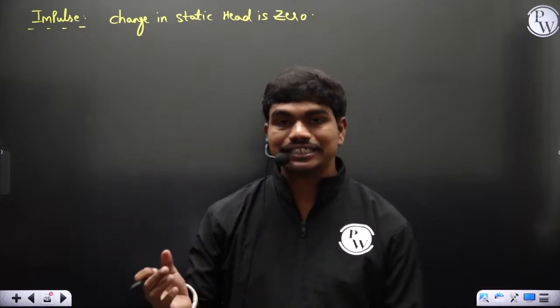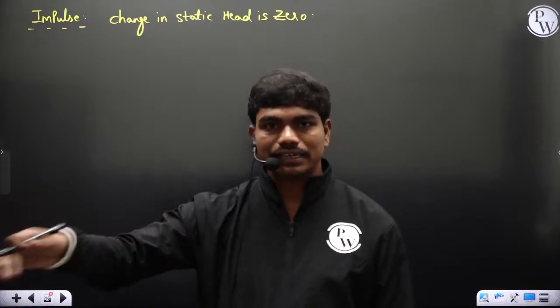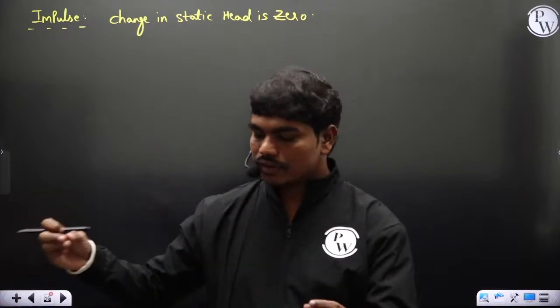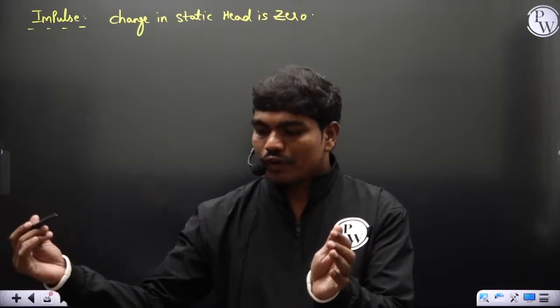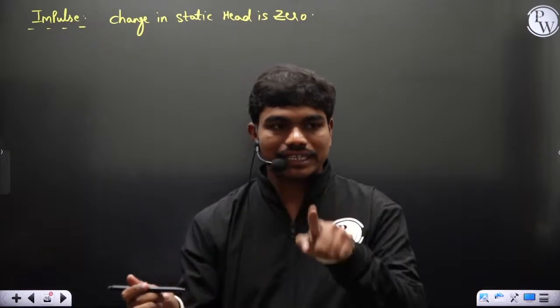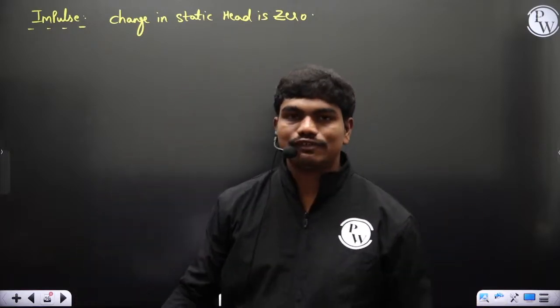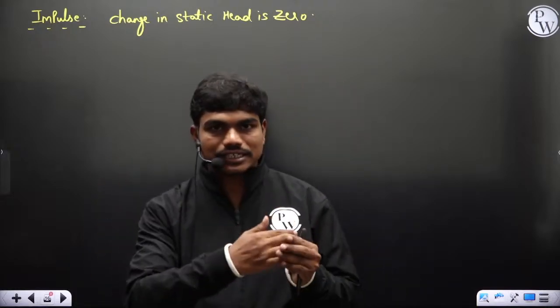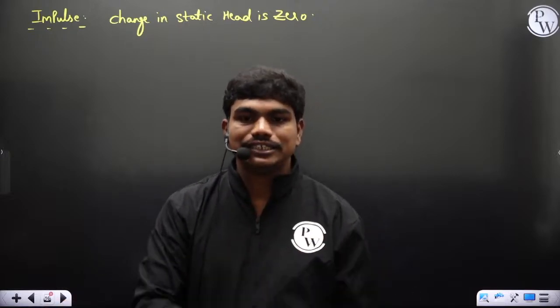No pressure energy is available at the inlet to the rotor. When the fluid comes out, nothing changes, so pressure energy remains the same all over the rotor. Suppose you take the rotor as a chamber: whatever pressure energy the fluid has when it enters, the same is available when it comes out, and the change in static head is 0 for impulse machines. That's why the name is impulse. Whatever power is generated is only because of the impulse impact of the fluid, nothing due to the change in pressure.